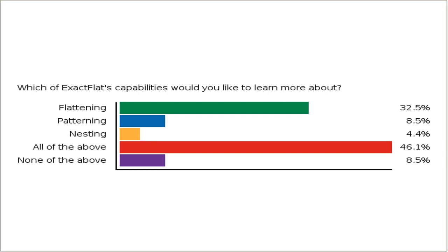Okay. Another question was, how did you get to the first image of the seat with all those pattern pieces, the one that you started off with? That was modeling. That particular one was a digitized car seat. We took a probe-based digitizer, digitized in the edge geometry, surfaced it, and then mirrored it. And so there's a number of ways that the initial geometry can be created. Because SOLIDWORKS supports a variety of inputs, a variety of file types, we often work with STEP or IGES files that get imported into SOLIDWORKS, laser scanned input, and digitized input as well.